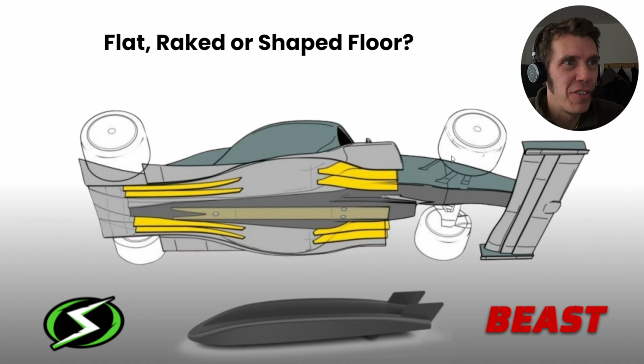Thirdly, I wanted to look at, with the knowledge that a lot of racing cars do some quite funky things with their floor. Like, for example, they might have a diffuser shaped like the inverse of an aeroplane wing. So in cross section, it starts a long way from the ground, and then it gets closer to the ground, and then it goes away from the ground again in this sort of diffuser section at the rear. And they also have all these funky turning vanes. I was interested to see if something like that could be useful for RC speed running. Although I did have in the back of my mind that if I went for something like that, it's going to be a lot harder to manufacture than the flat options, either the flat or the raked.